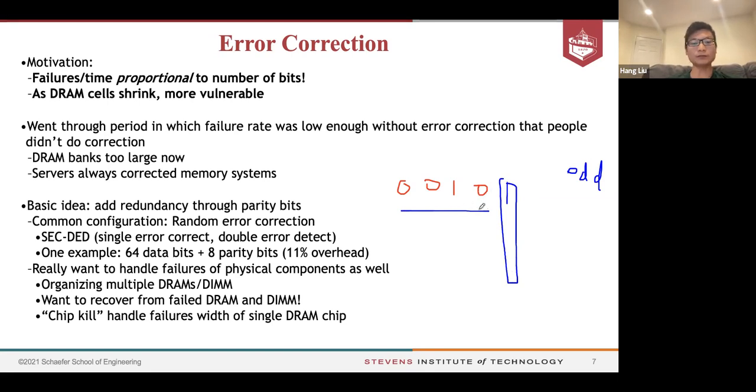So that's what we call single bit error detection. There are also 2-bit error correction schemes, and many other ways. But typically, for every 8 bits, we add 1 error correction bit. That is 1/8 of overhead, both for reading the data as well as storing the data.